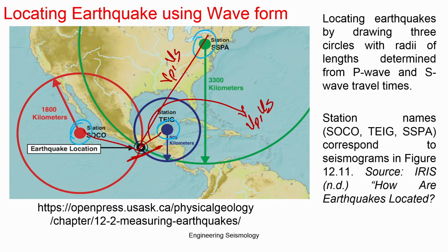Similarly, this velocity will be different as the geological terrain varies. The wave characteristics are a function of the stiffness and density of the geological material. The P wave is a function of the constrained modulus, and the S wave is a function of the shear modulus of the material. So that varies, and then these values also vary.